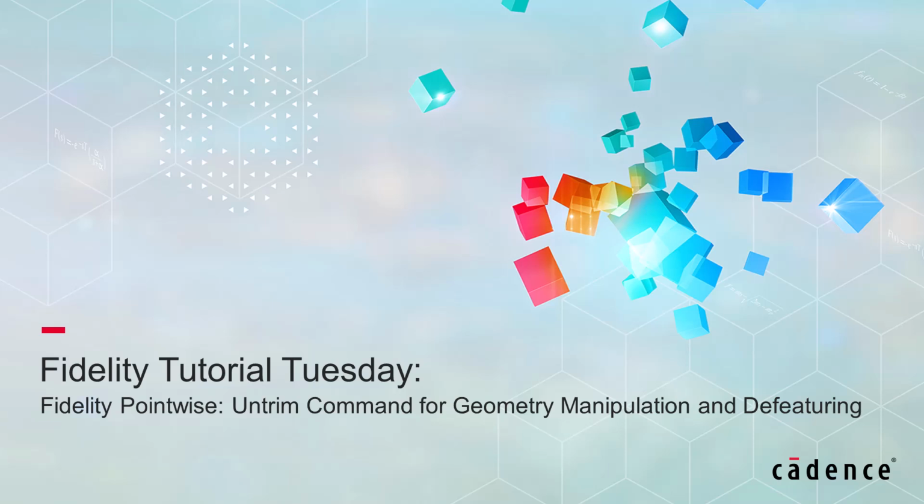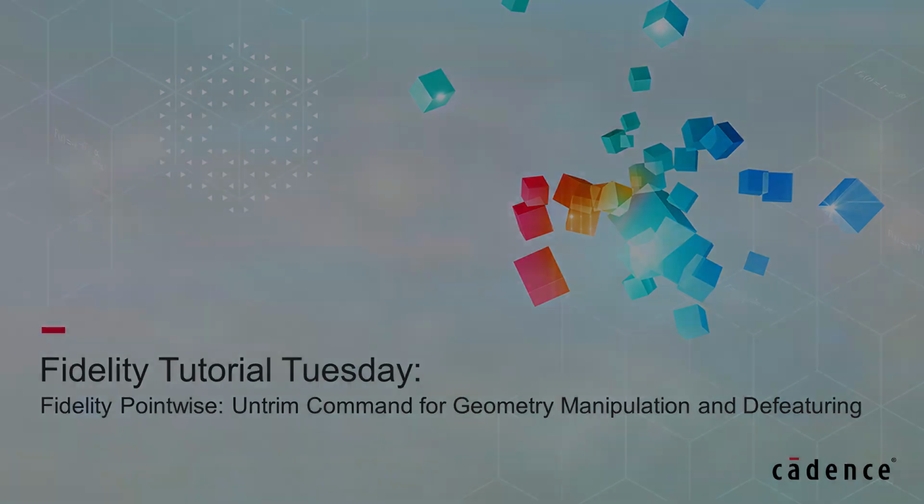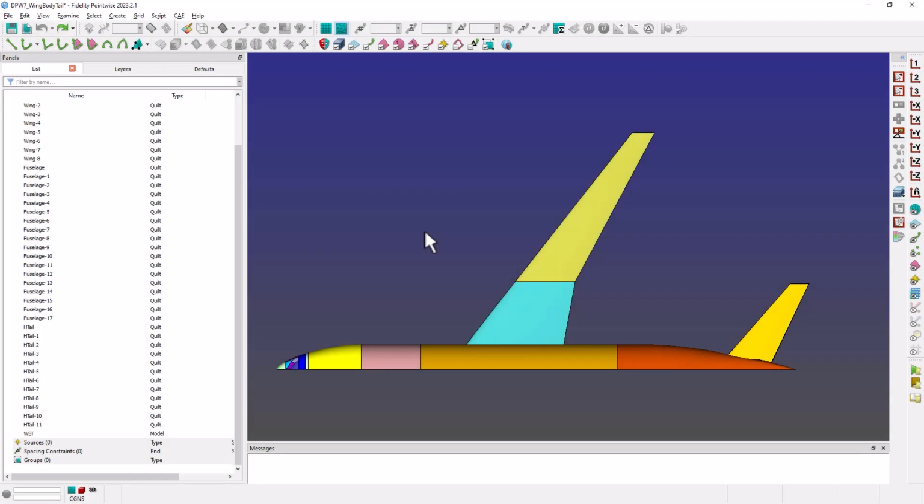Today we're going to see how you can leverage the Untrim feature in Fidelity Pointwise for geometry manipulation and defeaturing. The Untrim command in Fidelity Pointwise allows you to selectively remove trim curves from the boundary or interior of a quilt. This would be a very useful tool for defeaturing the quilt geometry to remove unnecessary details or to